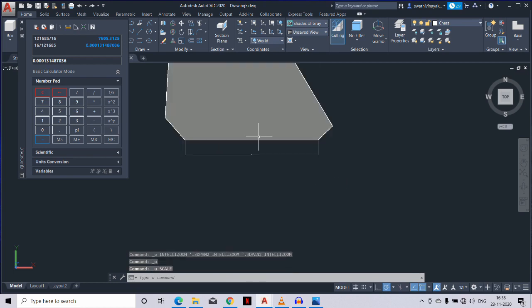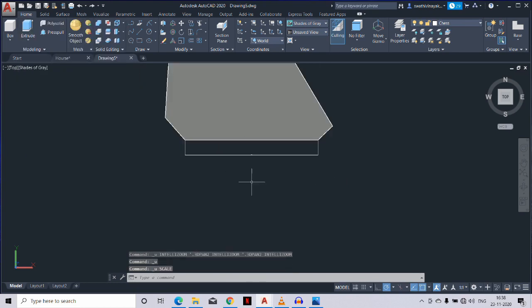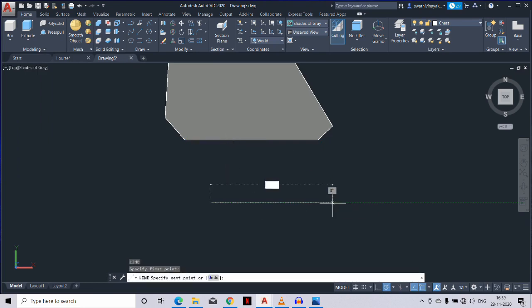The second value is align. Just close the tab. Just select it, we're going to press D for erase. So AL space. We're going to draw a line of length 16. Now we're going to do align. The shortcut of align is AL space. Select the object that we're going to align space. Click the end, first point.